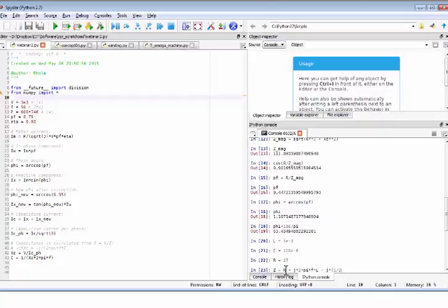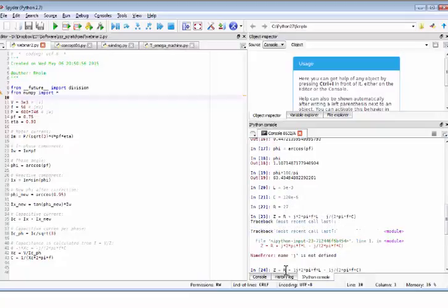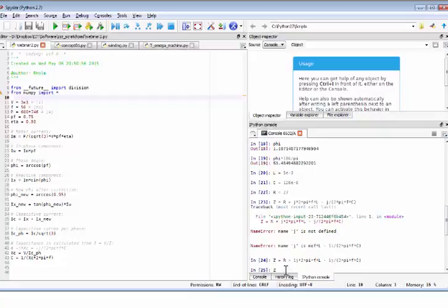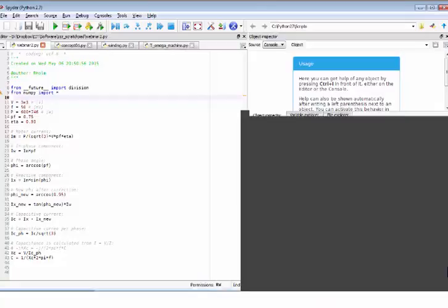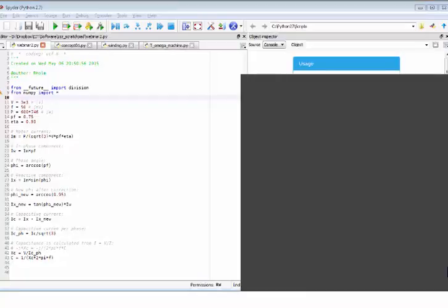But we don't have to have a 1 there. We can just say j divided by 2 pi f and c, like that. So this should work out. Right now it complains about j, so I'm just going to place a 1 there to indicate that it's a complex number, so this should work out to 27 on the real axis and 24.9 on the negative j axis.